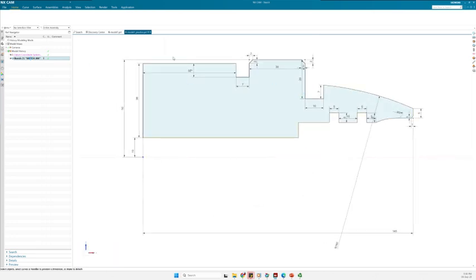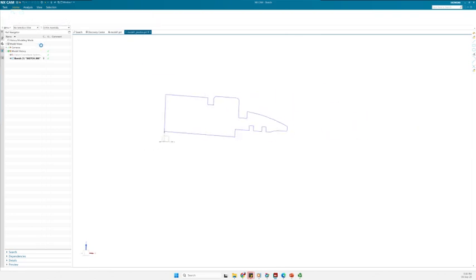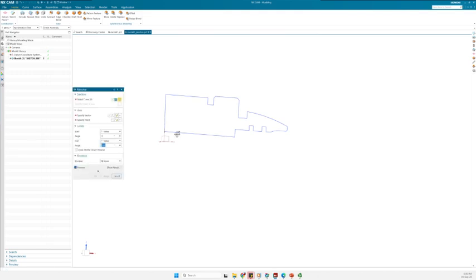And after making the sketch, pay attention that I made the sketch already in the ZX plane, so that the axis would be on X. Then after that, the sketch is finished. Then here I will be revolving this closed sketch. I will be running the command here, closing my curve. Then after that, I will select the point here, and then also the vector, which is this one. And now I have my curve here.